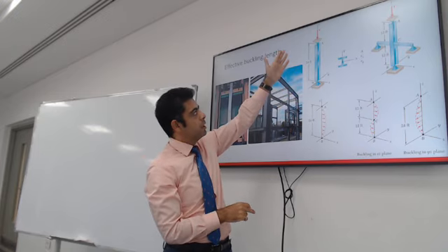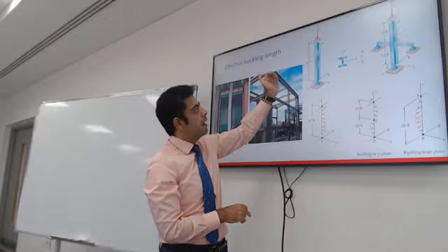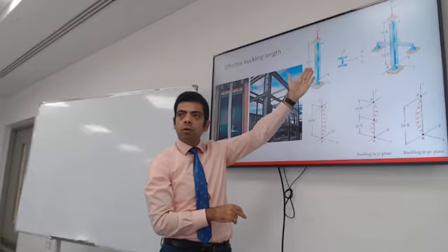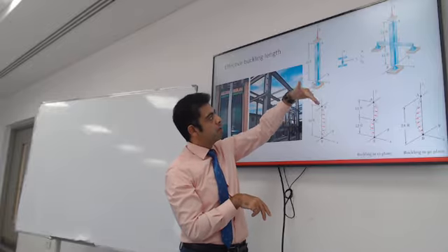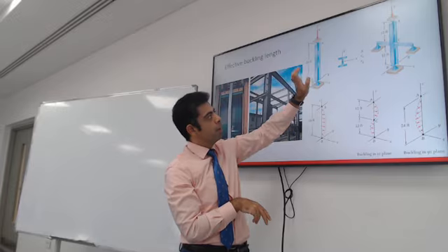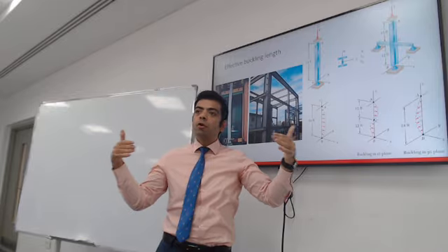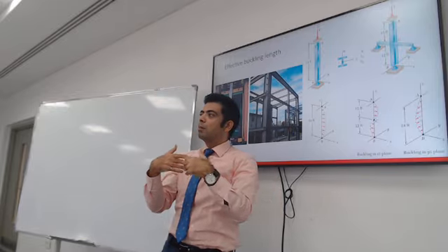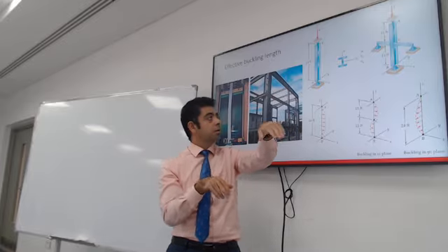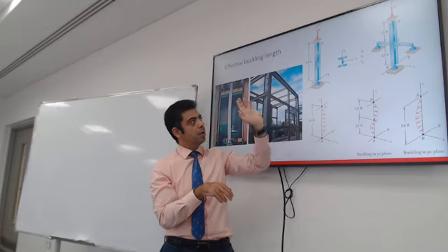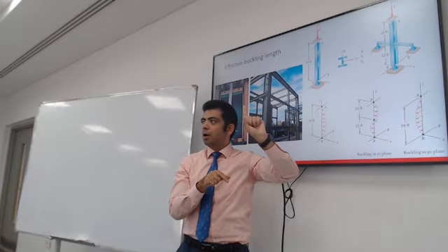If the whole thing is 7 meters, the buckling length with no side beams, which direction is the critical buckling direction? Is it outside, like about y, or about x? For a column that has no beams framing into it, when it buckles, is it going to buckle about x, or is it going to buckle about y? Like, is it going to buckle in the x direction or in the y direction?